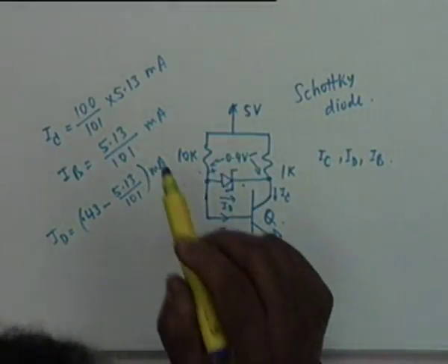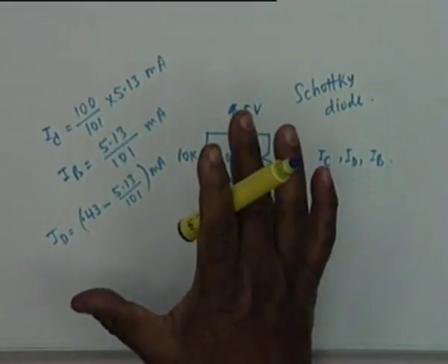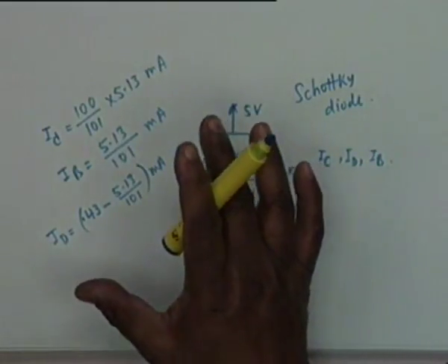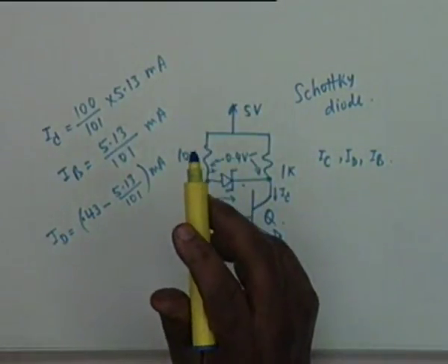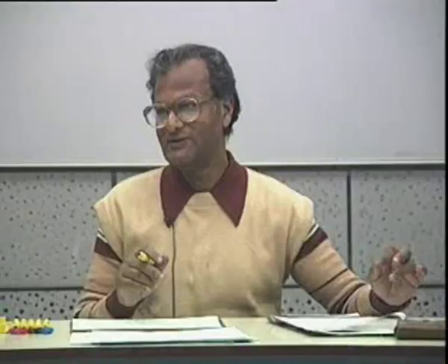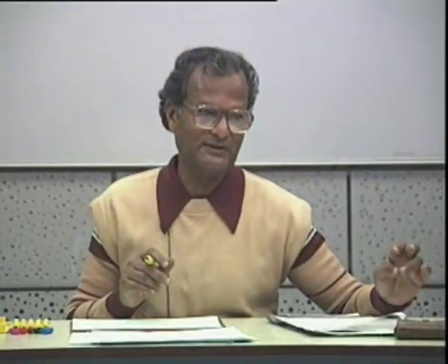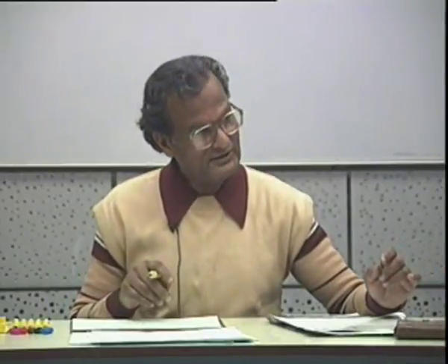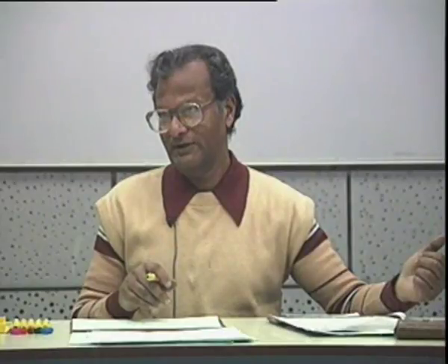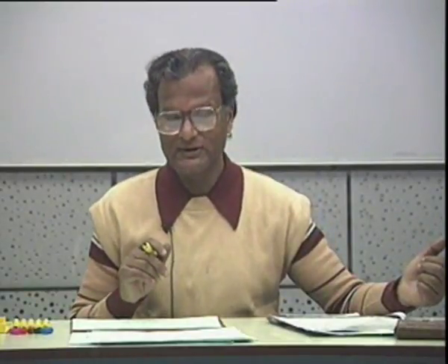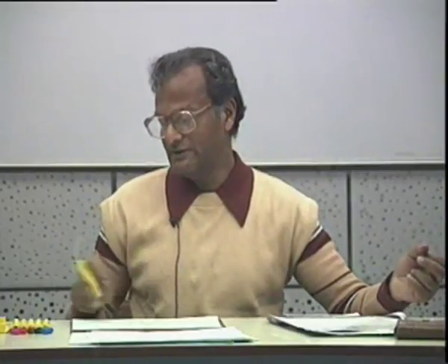And since these equations are consistent, our initial assumption that the transistor is in active region is justified. If this was not consistent, then you would have recalculated. Alright? Our next tutorial and next problem session will be on FET, DC analysis of FET circuits.